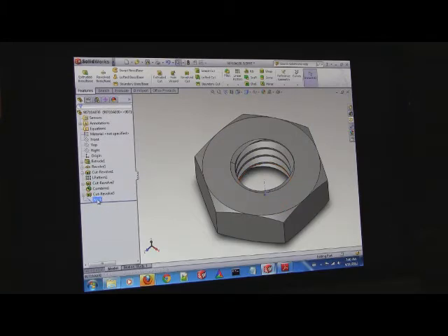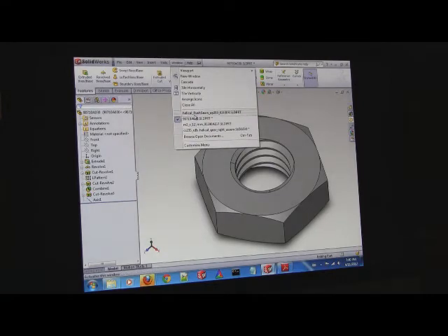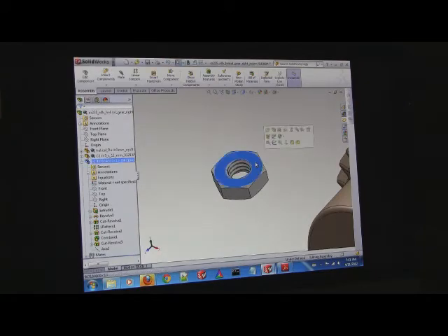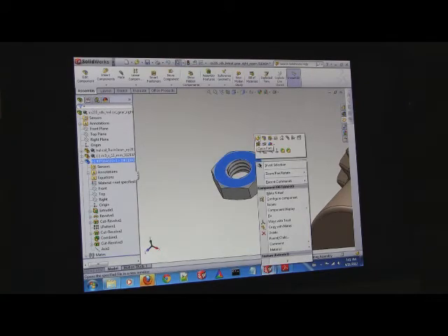Sweet. It's right there. Can you do this within the part file versus something? Within the part file. Anytime you modify a part, it's the safest practice to modify it in the part. Editing parts in the assembly mode is very tricky business. One of the most common ways of crashing SolidWorks. It just gets very angry. Ruben, can you repeat the stuff where you're opening? All you do is click it, right click, open.